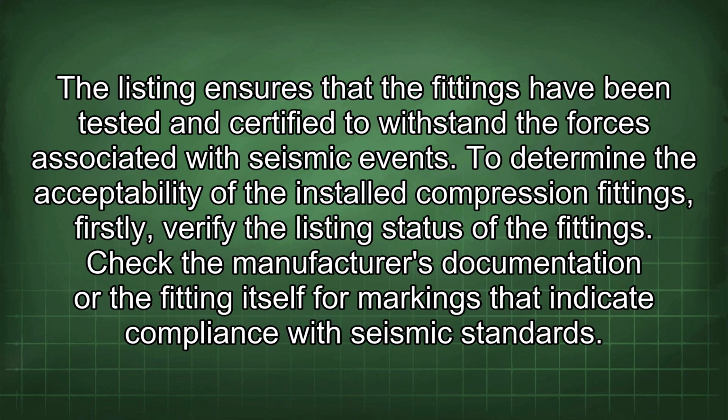To determine the acceptability of the installed compression fittings, firstly, verify the listing status of the fittings. Check the manufacturer's documentation or the fitting itself for markings that indicate compliance with seismic standards.